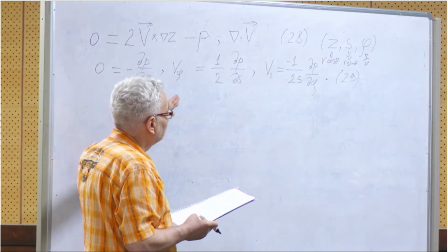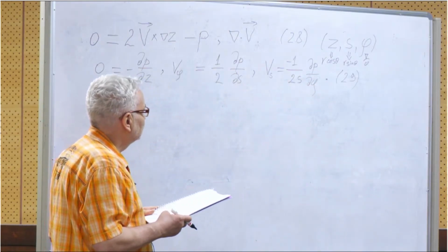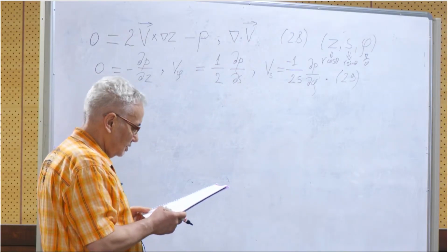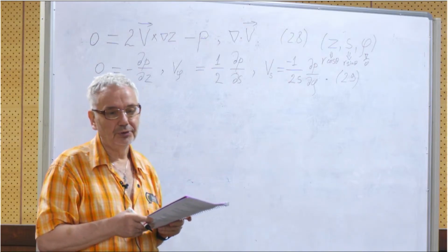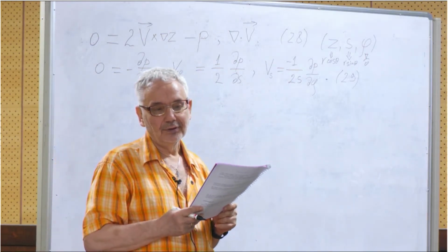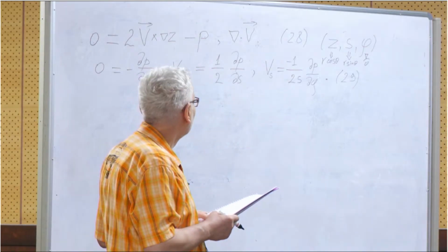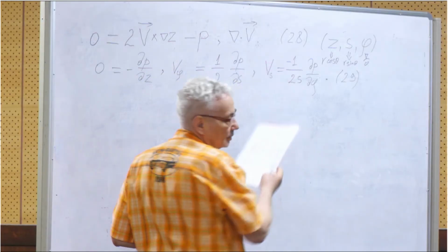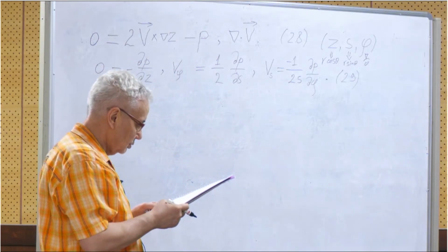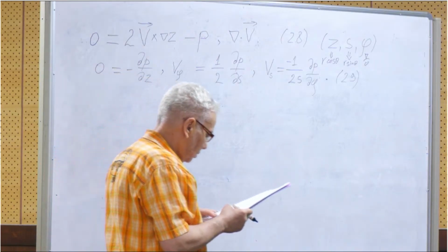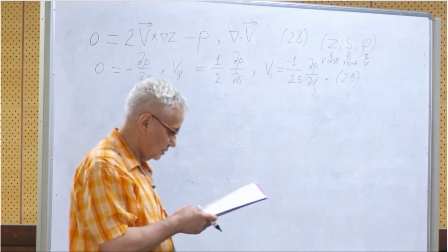Or maybe first, if we consider it in terms of the cylindrical coordinate, this component, which is directed along the axis of rotation, what do you think we should use to get it? We already used the Navier-Stokes equation. Which equation remains? So we should use the divergence equation to obtain this z coordinate of the velocity.